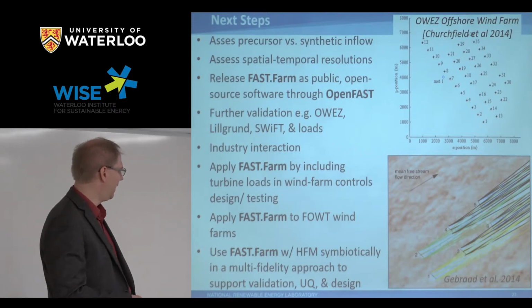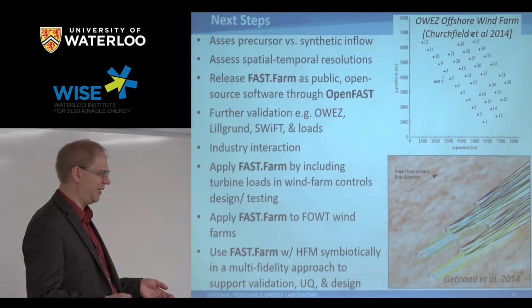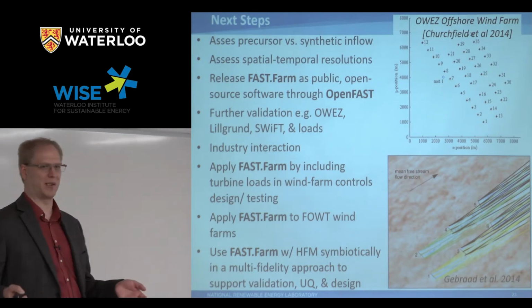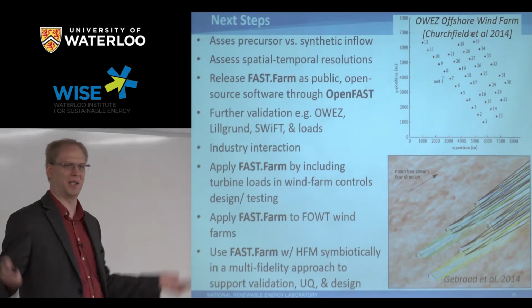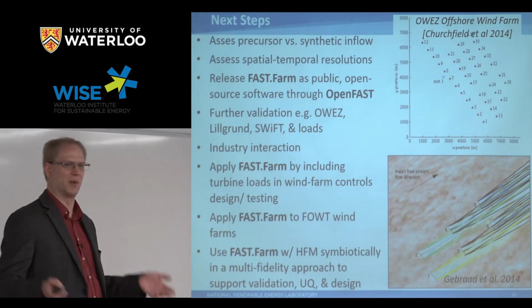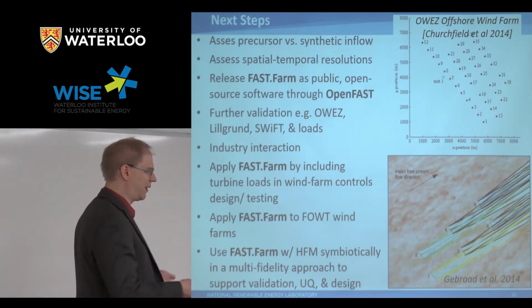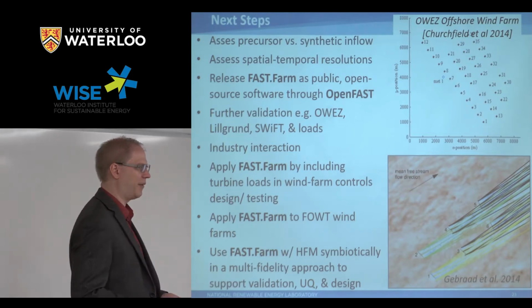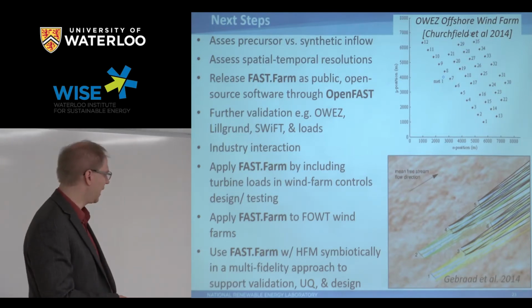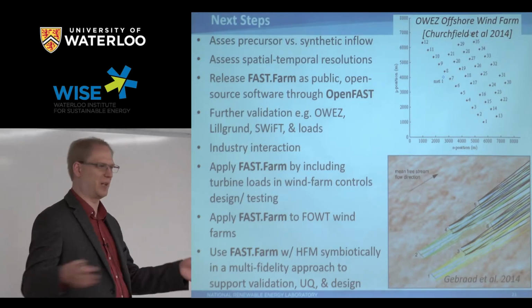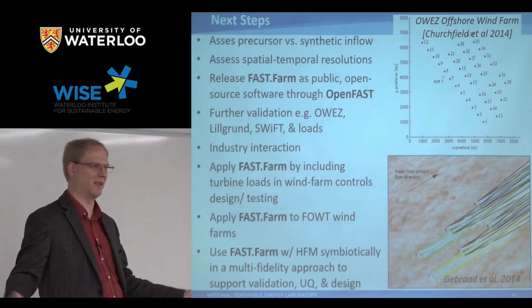Then finally, what I really see in the end is you're not going to throw away high-fidelity simulations. You're certainly not going to throw away low-fidelity simulations. What I really see is it's a multi-fidelity world, and we need to apply these tools in some combination that best makes sense. And so I showed clearly how you can calibrate this model to match high-fidelity results. I think likely what you would do in a real setting is you probably pick a few critical cases. You calibrate the model to make sure it works across those cases.